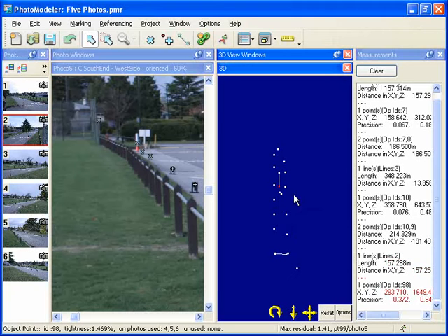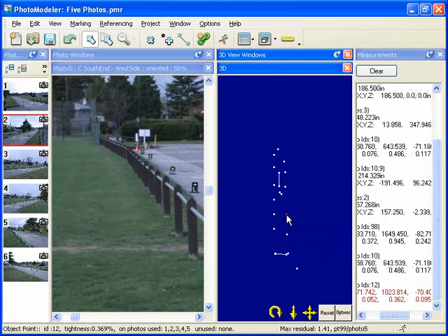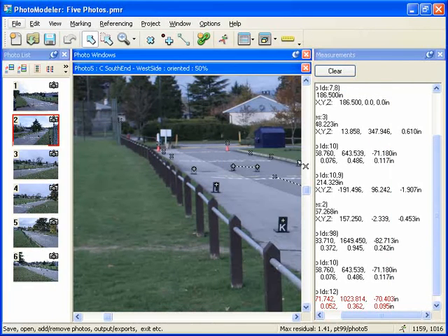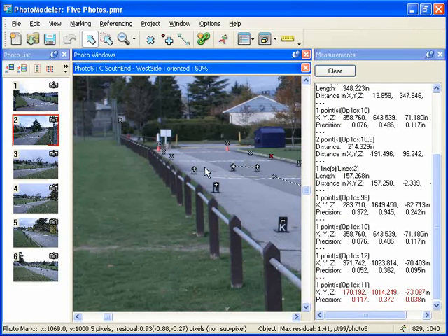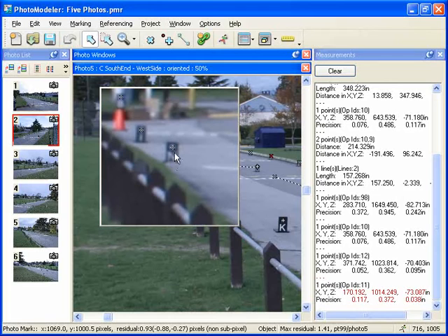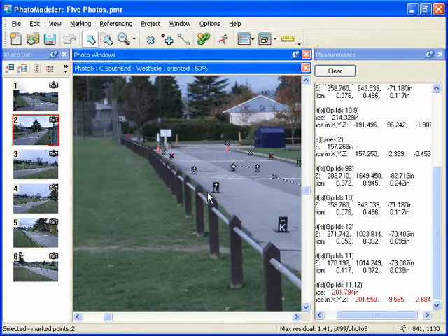It is a good idea to take several measurements at the scene. These measurements can be used as a check to verify the PhotoModeler project is solving well. In this case, we know the distance between evidence markers D and N was measured at the scene as 202.0 inches. Select point D, hold down Shift, and select point N. PhotoModeler's measurement is 201.79 inches.